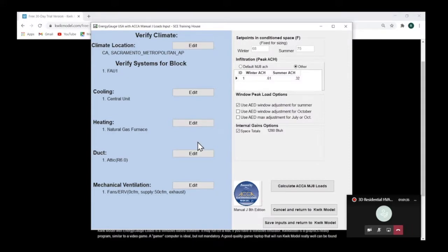And if the leakage is really, really bad, what you should do is tell the homeowner you should fix the house up. I do not want to design. I have a personal philosophy. I refuse to design an HVAC system for a crappy house. Okay, I just refuse. It's against my basic philosophy of HVAC design to design an HVAC system for a really crappy house. So what that means is, it's just kind of a silly way of saying, fix the house. Instead of oversizing equipment for a crappy house, fix the house, seal the house up.